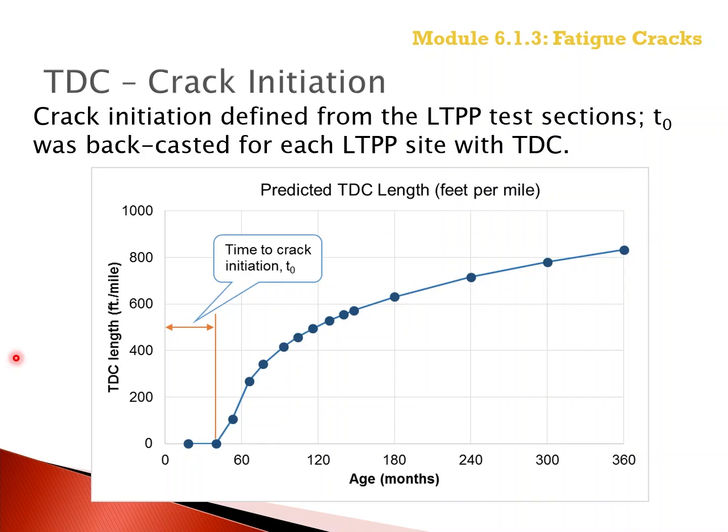The crack initiation is not included in the LTPP database, as we previously mentioned, or in any other data set when the global calibration process was completed for top-down cracking. As such, the time to crack initiation had to be backcasted using the time series data for top-down cracking.